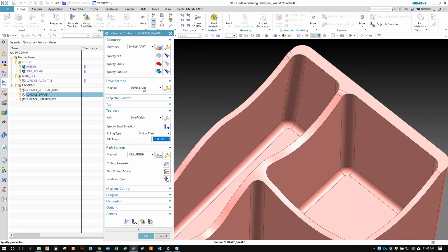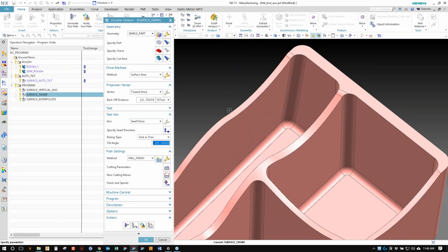It does not have to be the same surface as the part, but in this case that works well. So I didn't have to draw a reference surface, but you can draw a reference surface, and that gives you some control of the way that it projects the toolpath, and it can also give you control of the vector of the toolpath, which I've gone over in previous webinars.